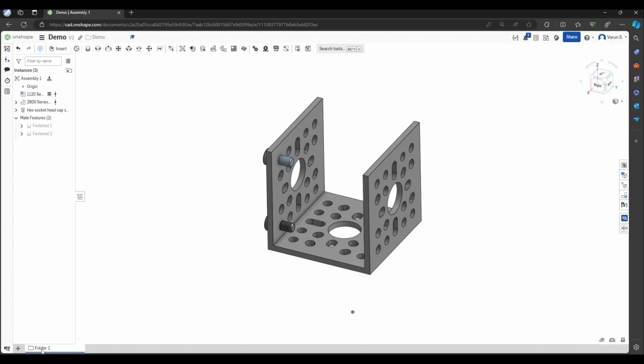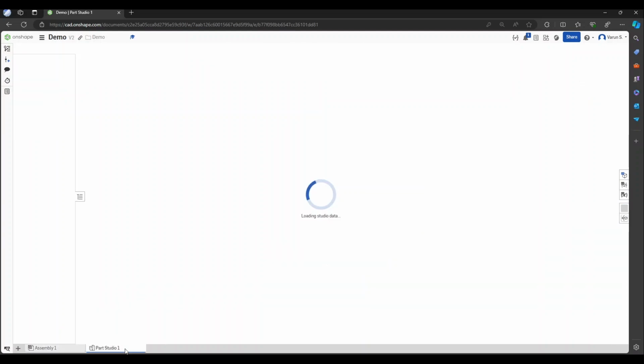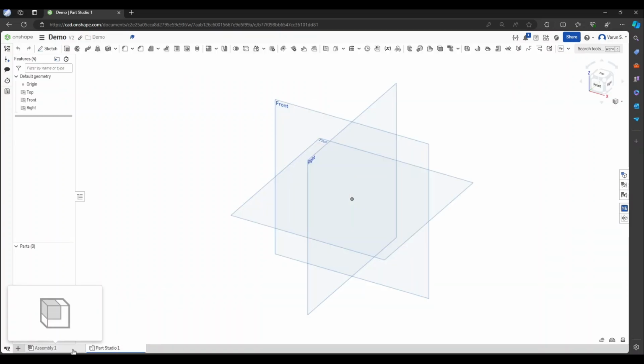And so now if I wanted to get everything out of there, I could right click on this assembly 1 and move to parent folder, which essentially just gets it out of folder 1. So if I were to hit that, it would then move out of folder 1, right? Or the other option is you can right click on folder 1 and just unpack, which gets rid of the folder entirely and just leaves everything where the folder used to be.